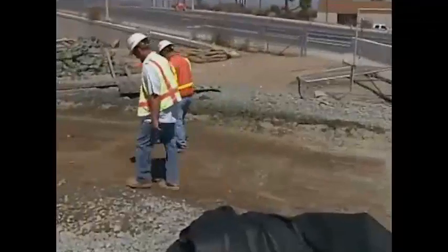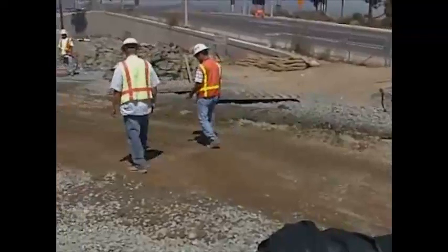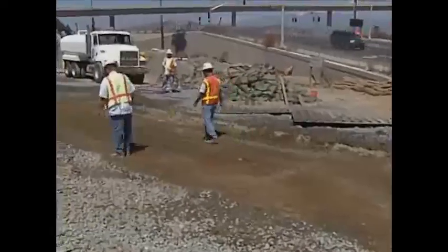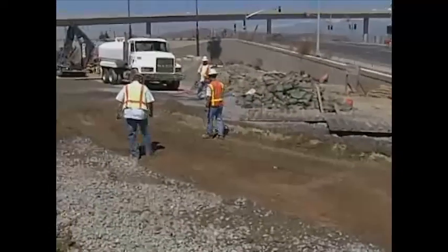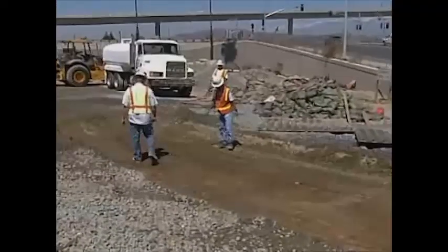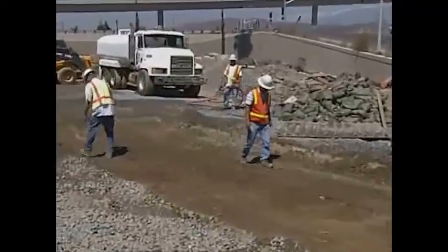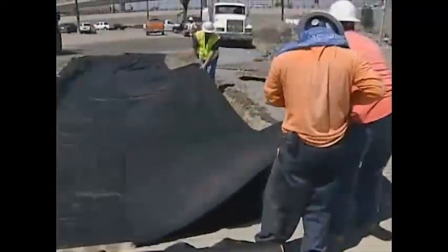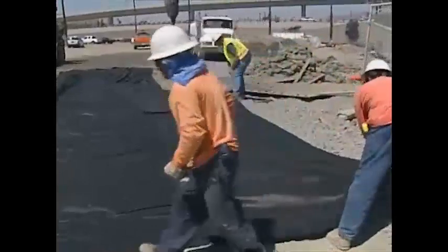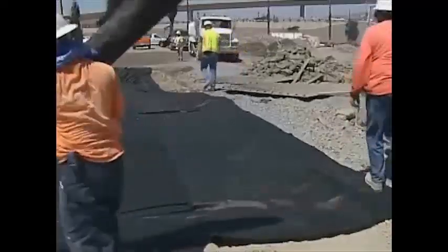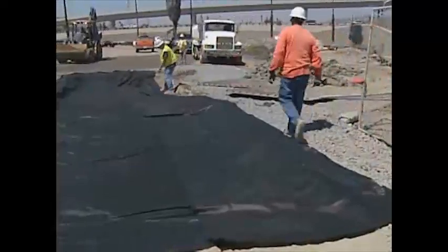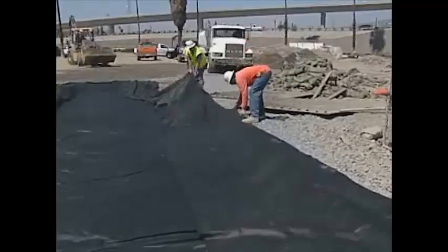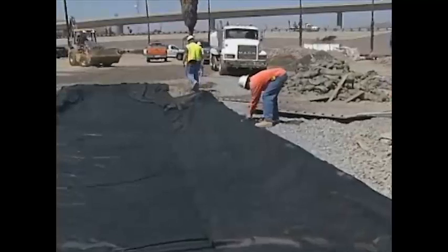Since a temporary entrance fabric is used to prevent underlying soil from migrating into the void space of the rock, ensure that the ground surface is free of sharp objects that may damage or tear the fabric before placing the temporary entrance fabric. Position the temporary entrance fabric longitudinally along the alignment of the entrance, as directed by the resident engineer, and overlap the adjacent ends at a minimum length of 12 inches.